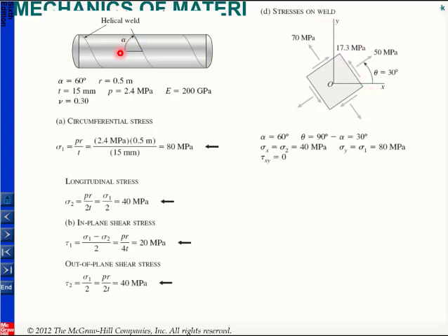So if this alpha is 60, basically this angle is given, the angle between my x and this direction. But I need to find my theta. So basically my theta will be equal to 90 minus alpha, which is equal to 30 degrees. So just be careful. This is 30 degrees, but this alpha is given as 60 degrees. And depending on the problem, they might give you different angles. But the idea is one of these lines should correspond to my welding line.